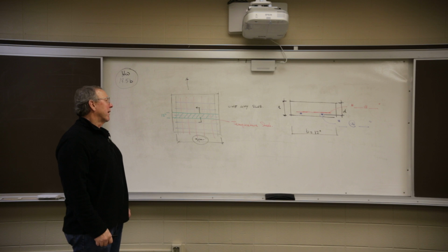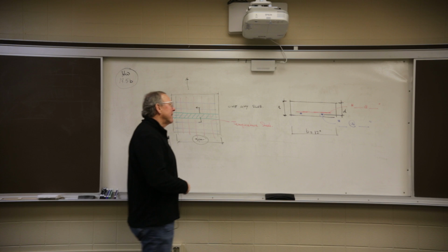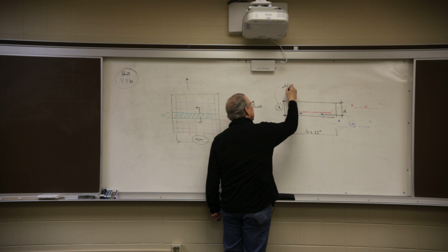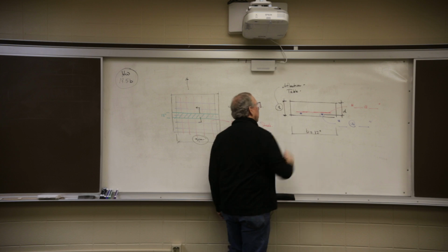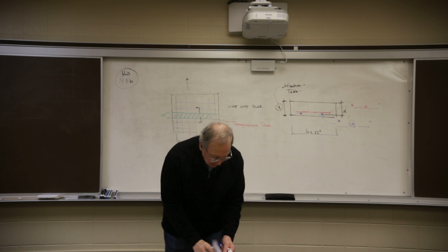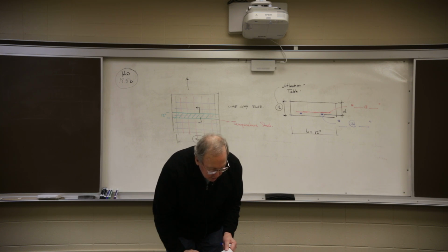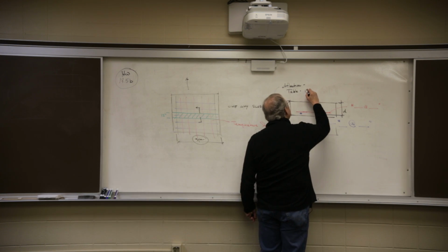So D and T are directly related. We'll do that in a second. And we need to design T, thickness. That is normally designed based on deflection and then checked. So we have a table. And we'll go through that table in a second. It is at the back of chapter 13. And if you want to look at where that physically is, that table is right after development length. And the table we'll be using is table 13.12 on page 478. Table 13.12 on page 478.